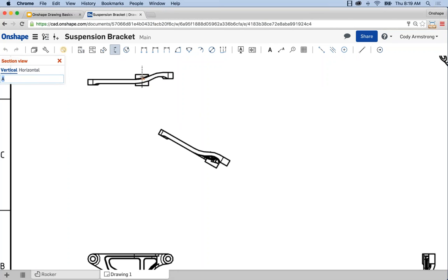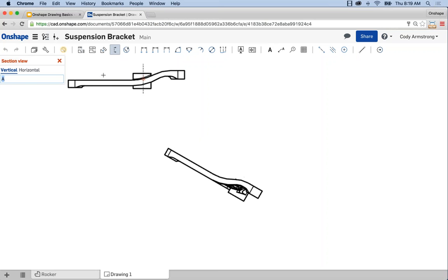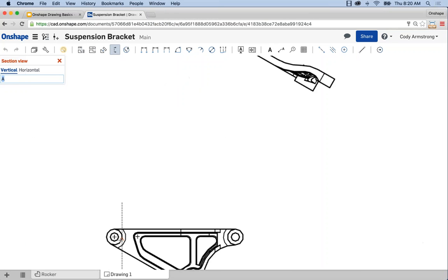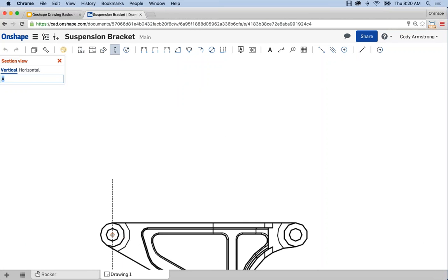Now this gets into the topic of attaching things. As I move my cursor over this drawing view, you'll notice these little indicators appear allowing me to snap. So that's snapping to the middle, for instance, and that's snapping to the edge. And if you look really closely, I'm not sure if this is going to come across in the GoToWebinar, but there are actually changes. So that's a square, that's a triangle, right? That's a square. If I move down, for instance, to this circle, it highlights the center point with a circle.